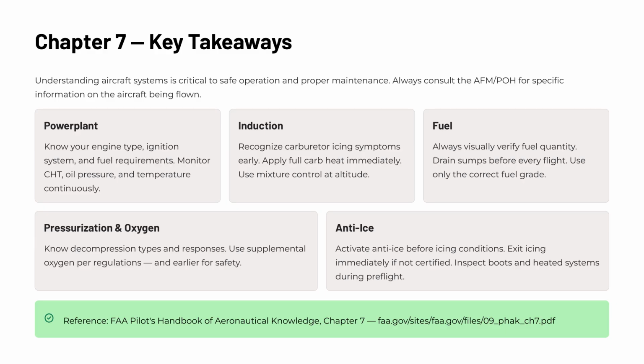On induction, don't wait for a rough engine to suspect carburetor ice. Recognize the conditions that create it and apply full carb heat proactively. Manage your mixture appropriately as altitude increases. For fuel, visual verification is non-negotiable. Drain every sump before every flight and confirm you have the correct fuel grade on board. Regarding pressurization and oxygen, know how to recognize and respond to decompression events and use supplemental oxygen earlier than regulations strictly require. Your judgment degrades before you notice it.